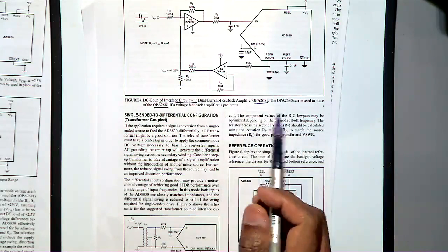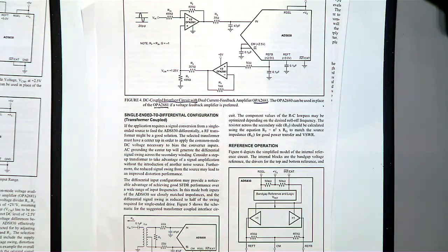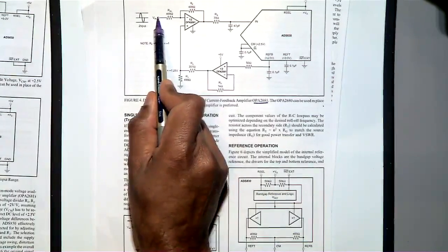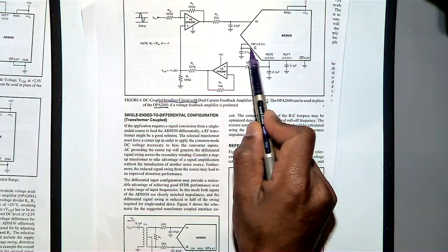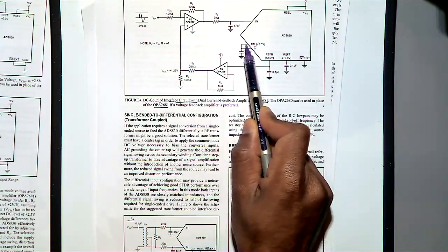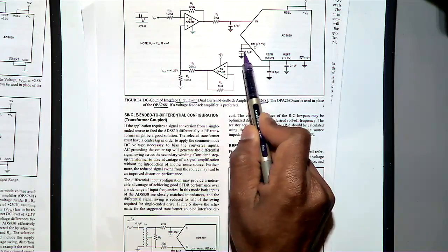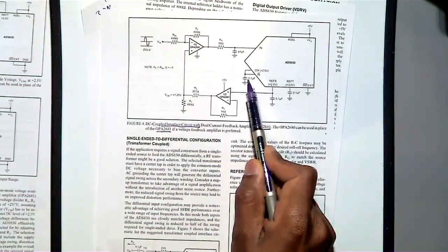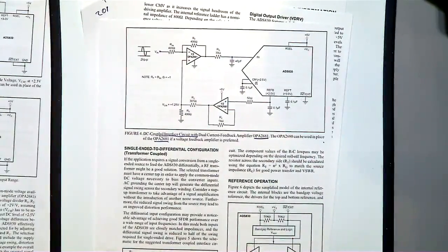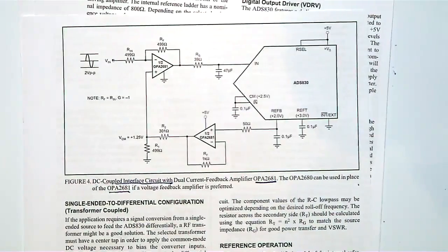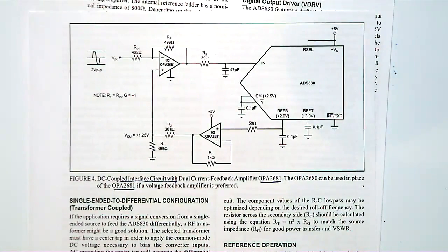So here, is it single-ended or dual-ended operation? Single-ended, because here there is only one input, and for the optional input of the ADC, they already said how to connect it. If you are not using the other optional input, then it connects to the common mode pin of the ADC, and then through a 0.1 microfarad capacitor to ground. See, that's how we will be doing it.